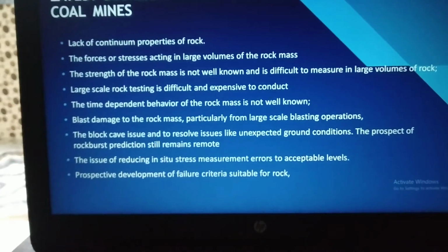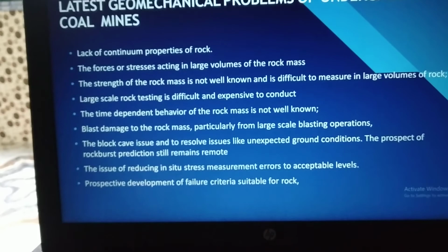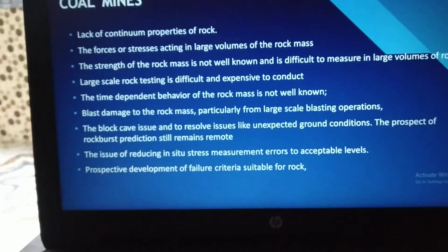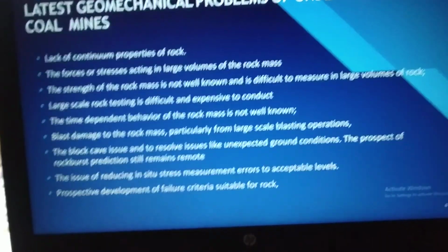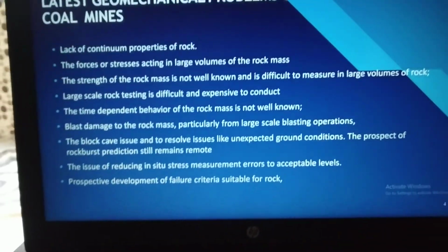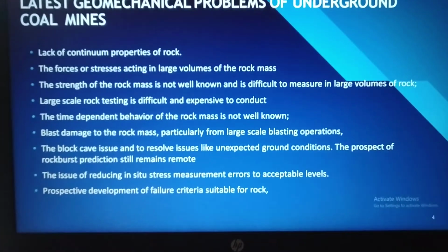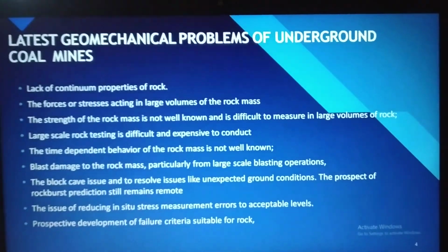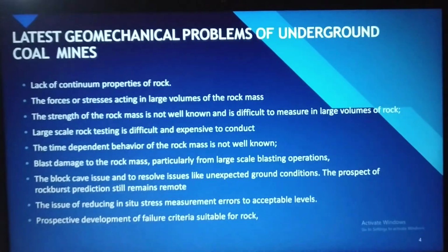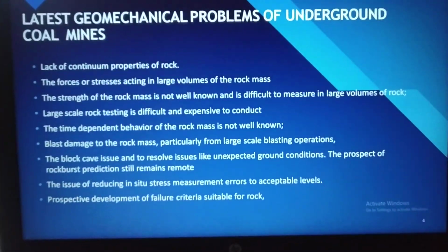The strength of the rock mass is also not yet known, and there are no particular formulas or derivations through which we can determine the strength of the rock mass. All those formulas which are there also depend upon the mining conditions as well as the depth at which we are mining. Then there is the time dependent behavior of the rock mass. The rock tends to change its properties, that is the porous nature, the brittleness and the continuous property as well. They all tend to change with time.